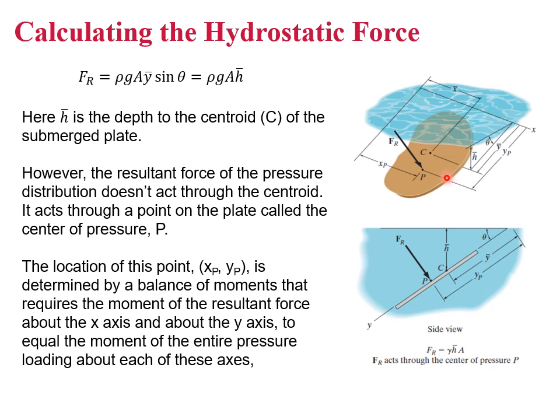Now notice in this situation, the total net force felt is at this point P. This point P is what's called the center of pressure. And notice the center of pressure is not the same as the location of the centroid. The location of the centroid would be X bar, Y bar. The location of the center of pressure is going to be X sub P, Y sub P.